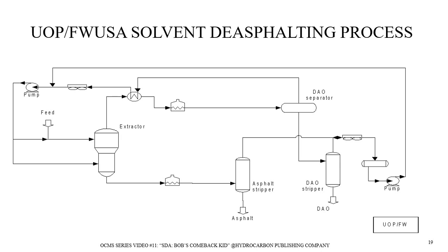This figure shows a process diagram for AMEC, Foster Wheeler and UOP's SDA process. UOP's SDA process has proprietary structured packing internals for the extraction column in fuels production, a rotating disc contactor for lubes production, and a 3-product configuration available.